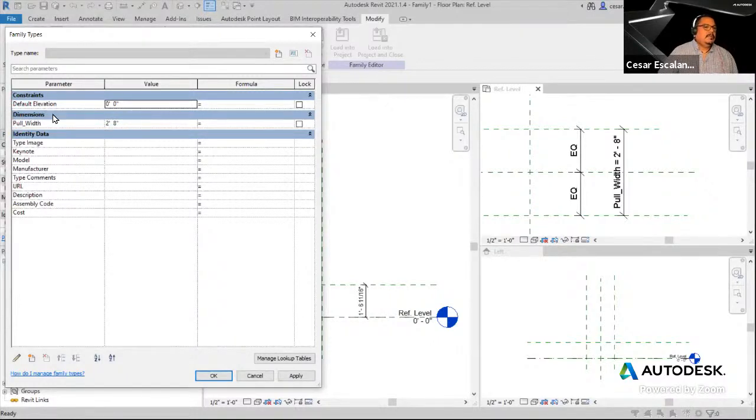And remember that dimensions group, that is what is telling Revit where this parameter is going to be placed under this family dialog box. You have like 20 different options of parameter groups, and you can organize it as needed. I pick dimensions because it's more logical. These are dimensional constraints, but there are others like energy, materials. There's another one, electrical, etc. All right.